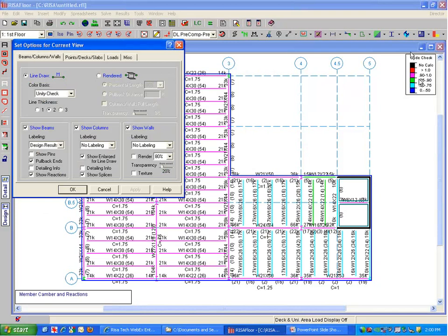When it's green, it's between 0.75 and 0.9. Those are the ones that are pretty stressed here on the right side of my screen. They're highly stressed compared to the rest, which is all pink, and pink is getting even higher, at 0.9 to 1. So everybody's even more stressed over here, which is good. I'm running closer to capacity, which means I'm designing at the limits, which is very good.